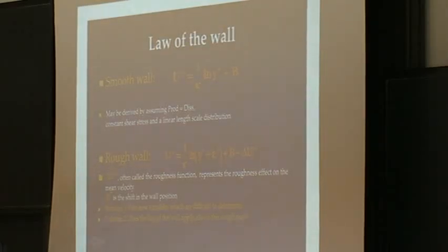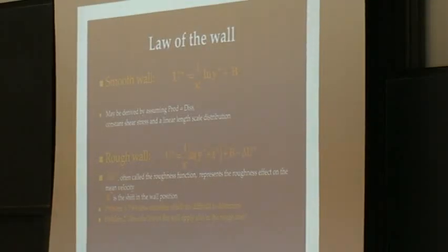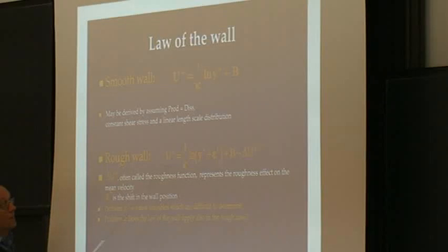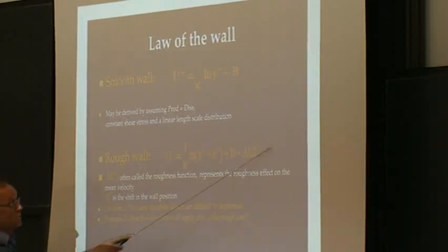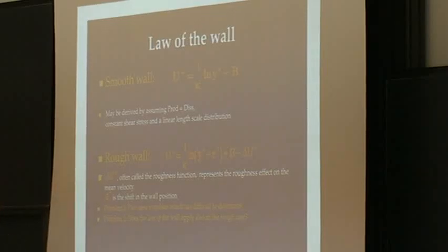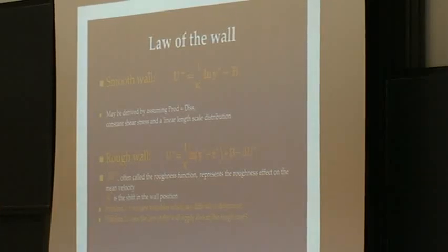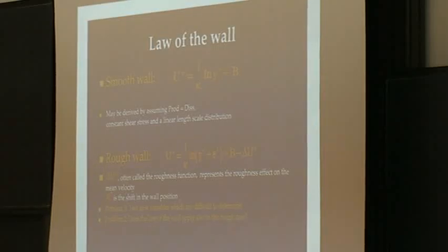It's very difficult to actually measure the shear stress. So most people tend to do some sort of curve fitting, either to the log law as such, or you can add the wake and then do a matching to the full profile. So you now have three variables that you need to extract from the matching technique, and of course we can see that that reduces the accuracy of all of them compared to the smooth case.